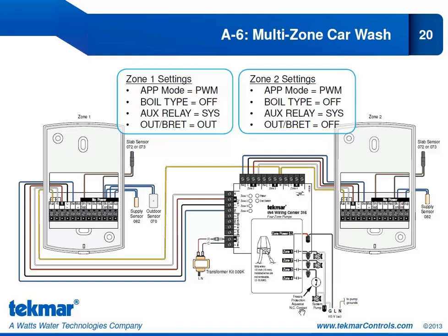And you can see the freeze protection aquastat is wired in line with that pump, so when we do approach freezing, we will open this normally closed contact and there will be no power at the system pump.